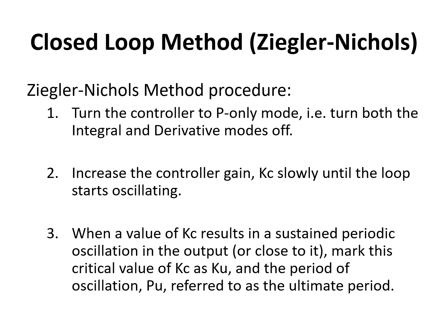So when you increase it slowly, you should get the loop to slowly start to oscillate until you get continuous oscillation for the response.